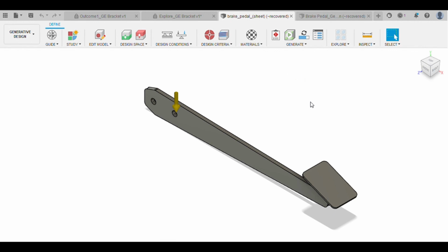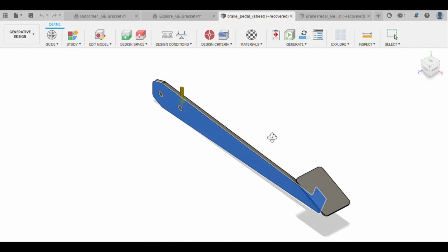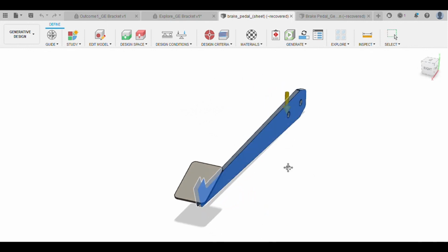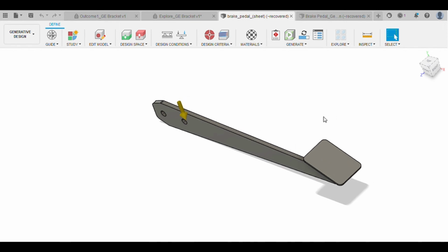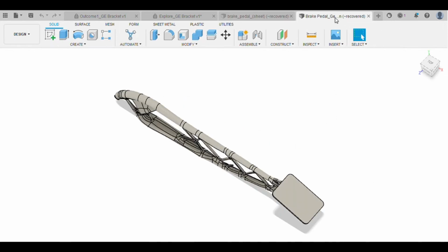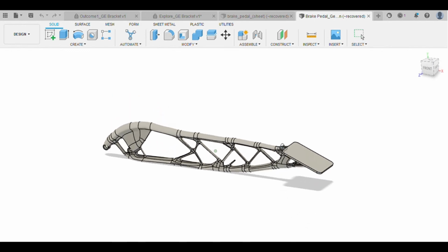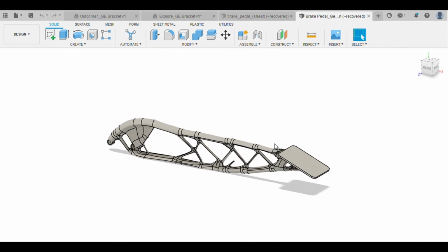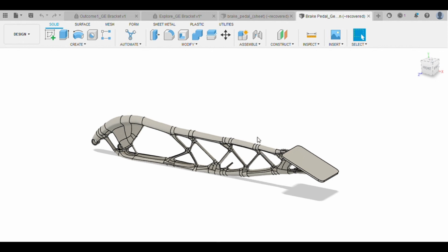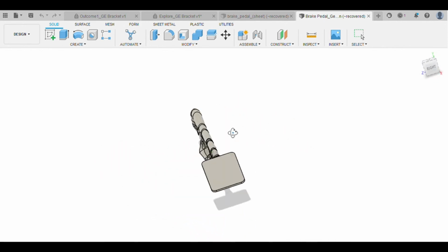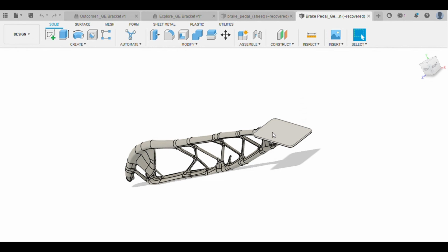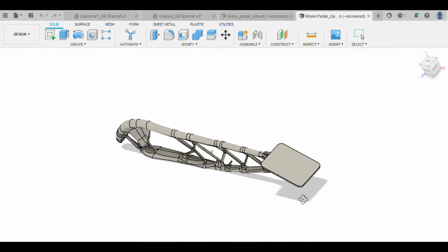So in certain major regions, the weight could be effectively optimized. So in those regions you could use generative design, and using generative design, this is the final model that I have applied. So obviously strength factors you have to consider. So considering the factor of safety, this is the design that we got. So as you can see, a lot of weight has been optimized. So here we gave the load conditions, with the newton values, and optimized as much as possible.